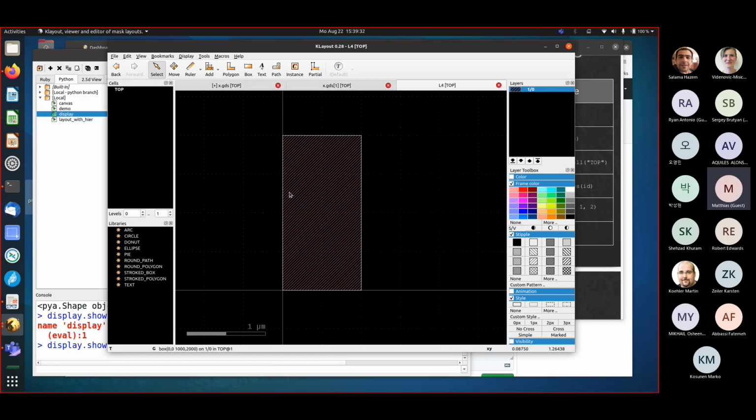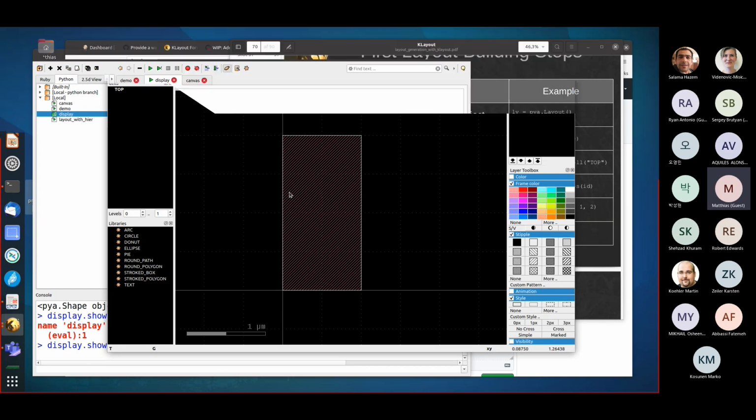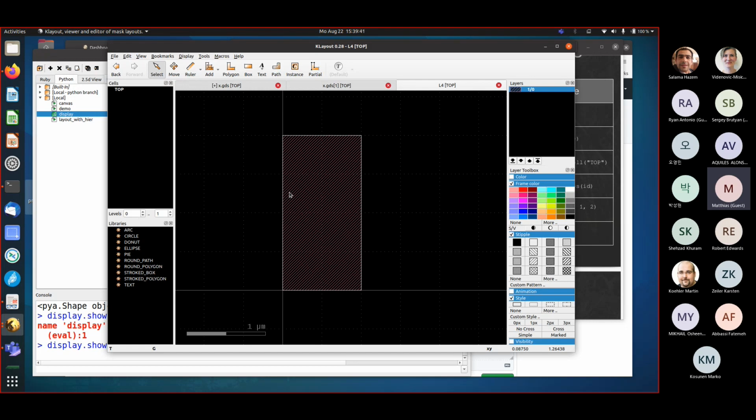And what we did now, we were talking a lot about these geometrical primitives, boxes, polygons, text, whatever, how to manipulate them. But this is how you publish them. This is how you assign them to a layer. So first step is we define the layers inside the layout. We get some IDs back, which are integers. Then I define cells, and then I attach these geometrical primitives to shapes inside layers, inside cells. And that's how I assign layers to polygons. Okay.